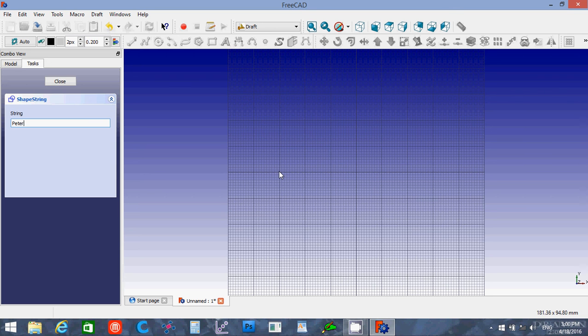If your name uses an I or a J, you're going to have to try to use all capital letters when you put your name in, because otherwise you're going to have what I call orphan parts when you 3D print. Basically those I's, the dots at the top, unless you connect them some other way or put a backing to the letters, then you're going to have a problem because they're going to be separate pieces when you 3D print it. You'll pop off the thing and go, oh, oops. So you want to be aware of orphan parts that can happen.